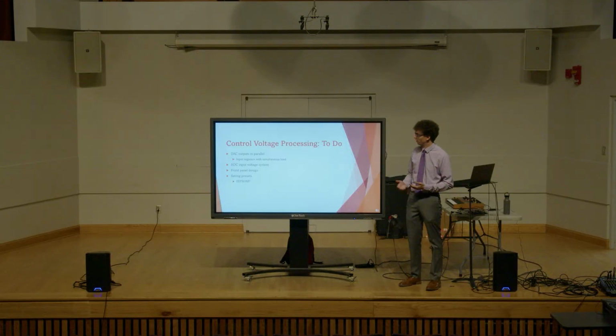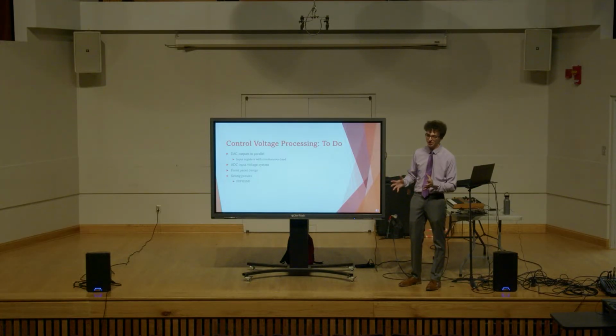So like I mentioned before, what I still would like to do is start running these multiple DACs on this one chip in parallel so I don't have to run every single control parameter in series. And that can be done very nicely since this specific DAC lets me update all of the input registers for all of these individual converters with their next level and then update them all at the same time, which is nice.